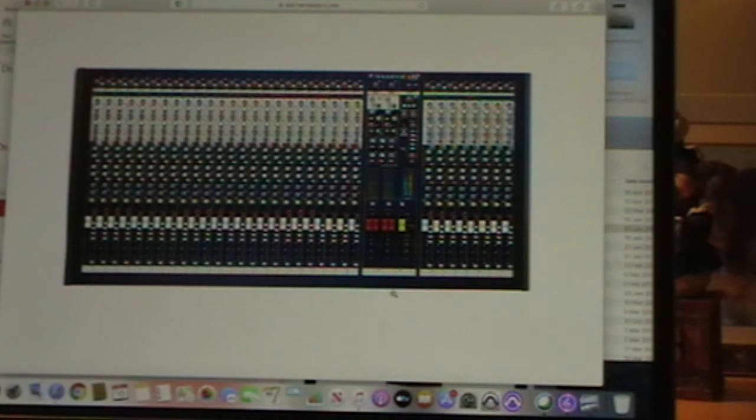The first section on an analog mixing console is a pre-amplifier, and the job of that is to control and boost the microphone and line level signals so that they can be effectively processed, recorded and played back. The controls and parameters on the preamp section include the input levels, gain, phantom power, and the light emitting diode LED for clip indicators. They have high pass filters and line level passive attenuation devices.